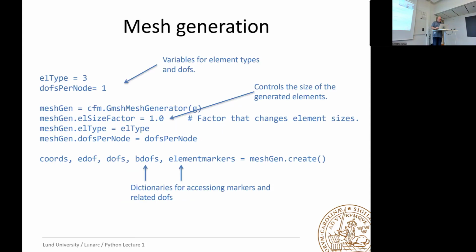Yeah, that was what I said. This next step, we need to call our mesh generator. So we specify here the element types. I think this is a 4-node element. We'll see. As this is a groundwater problem, we only have 1 degree of freedom per node. So we don't have a displacement here, we have a flow.